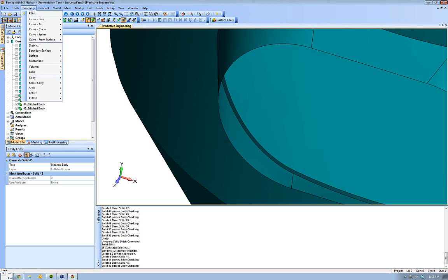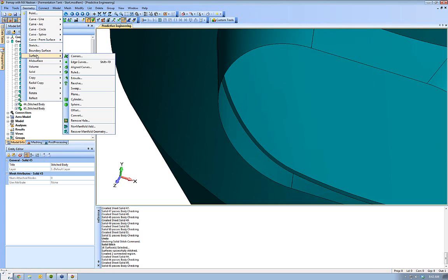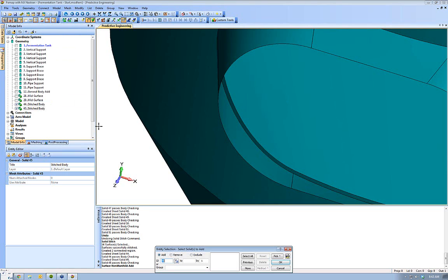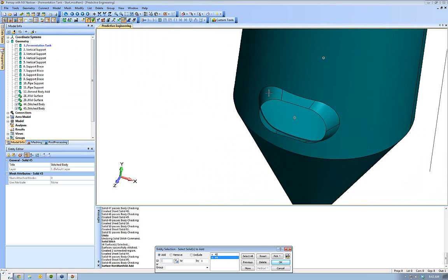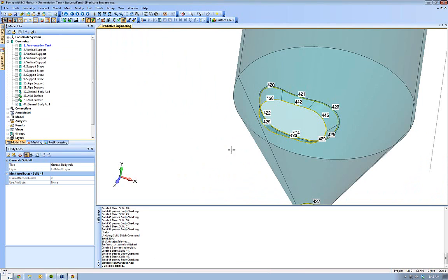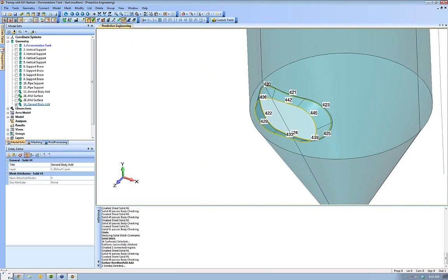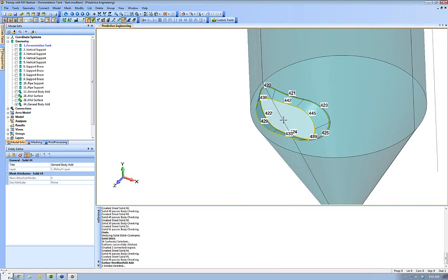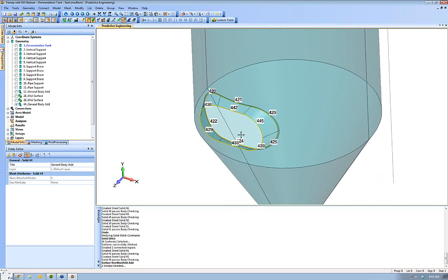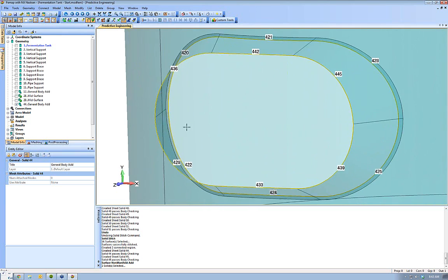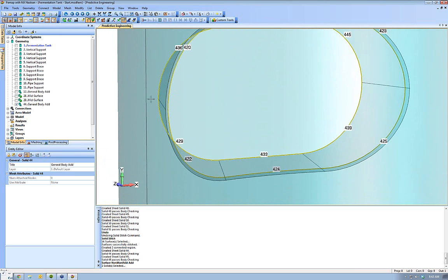So we're going to need non-manifold add: geometry, surface, non-manifold add. We're going to need this command to join these two parts together because of that complicated intersection. We click OK. You can see in the model tree it's all just one general body add now. And our only free edges are at the openings and at the edge of this little lip here. We can actually delete that. We can remove that before we move on.